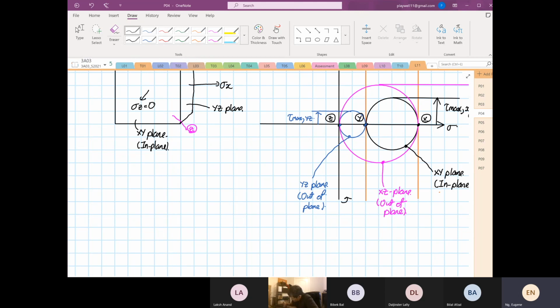You can solve it. I'll tell you where's the problem. So if we just analyze this problem with a 2D Mohr circle, right? So this is your stress X, and this is your stress Y. And you say, I'm going to ignore my Z because it is 0, right?